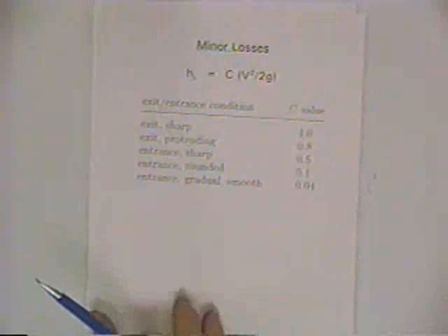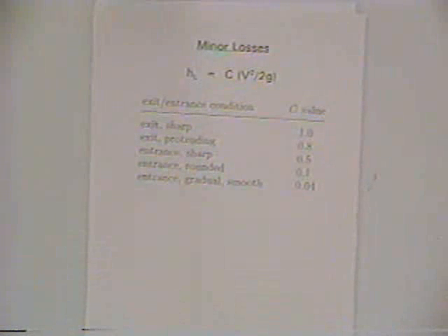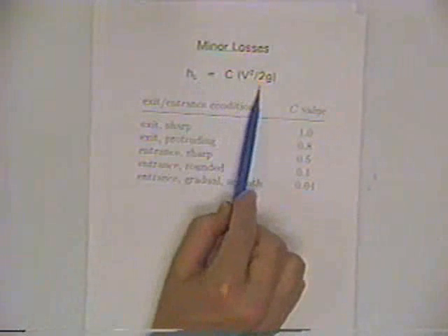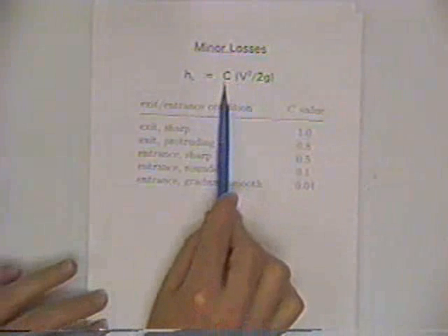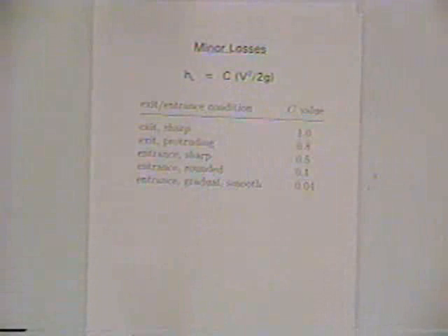And so a common term for these other head losses is minor losses. In many applications, the minor losses might be quite major, but that's what we call them. They can be expressed in different formats. In your reference manual, the formats are always in the general form of head loss equals some minor loss coefficient times a velocity head. Your reference manual uses the term C for the minor loss coefficient. In the literature, there are volumes that give minor loss coefficients for different types of valves, different types of fittings, and so forth.